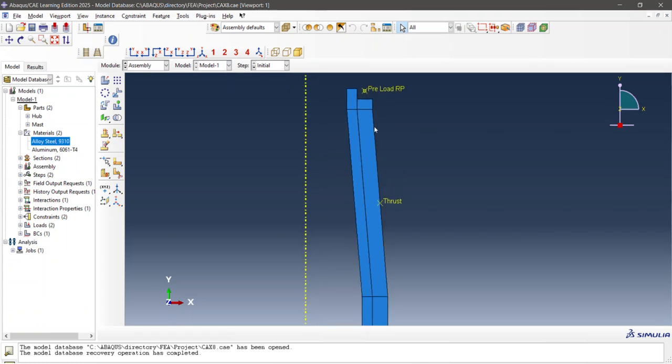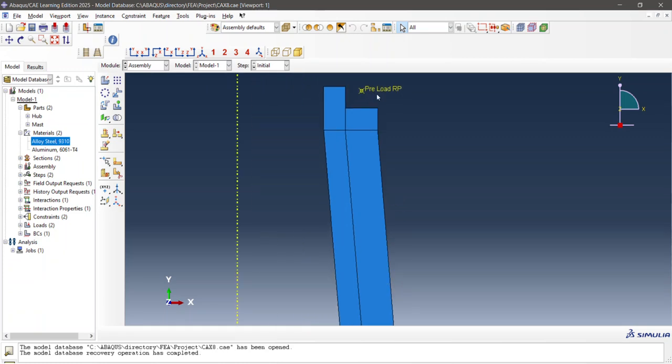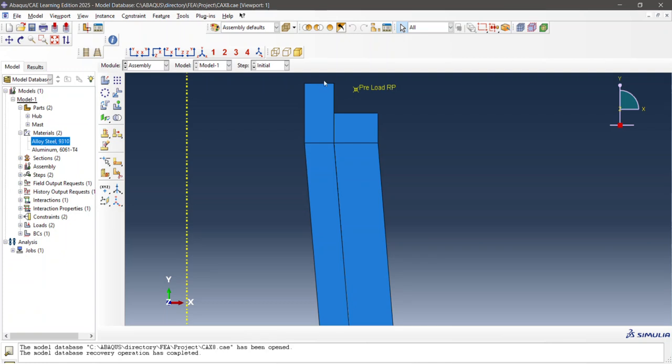So that contact pressure generates a hoop stress. That hoop stress is going to be applied from a mast nut. Now, a mast nut is threaded all the way around. Now, imagine this is 3D, right? It goes all the way around, one big circle onto your mast until it sits flush with the top of the mast and is also applying light pressure to the hub.